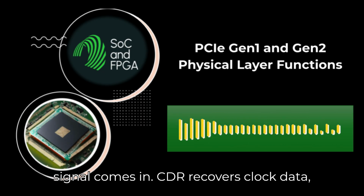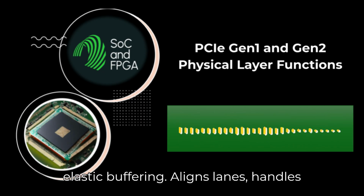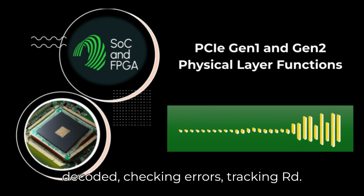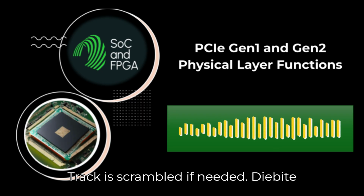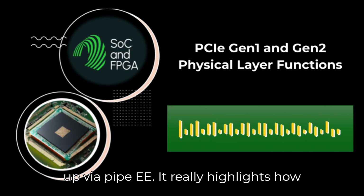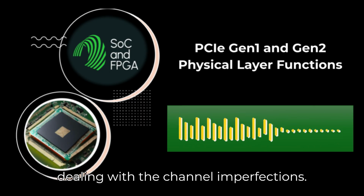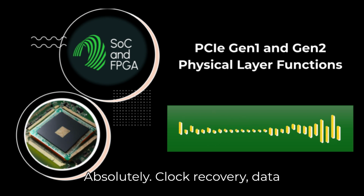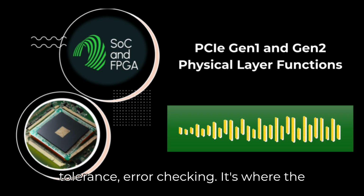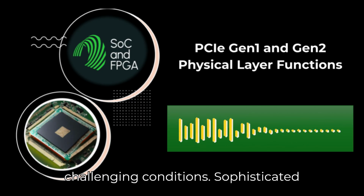Receive. Differential signal comes in, CDR recovers clock and data, deserialized by SerDes, lane-to-lane skew and elastic buffering aligns lanes, handles clock drift and domain crossing, 8B10B decoded, checking errors, tracking RD, descrambled if needed, byte unstriped, reassembles lanes, data goes up via PCIe. It really highlights how much more complex the receive side is, dealing with the channel imperfections. Absolutely. Clock recovery, data recovery, skew compensation, clock tolerance, error checking. It's where the analog meets the digital under challenging conditions.